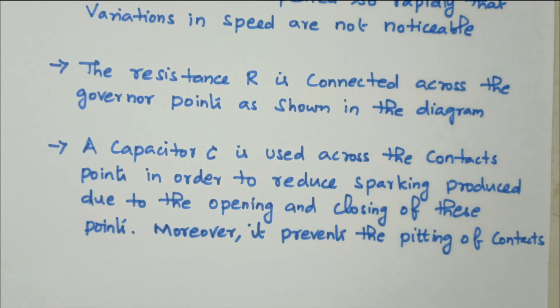The speed is set by the operator. We can set the speed accordingly. This centrifugal mechanism will open or close the switch. If the speed is high, it will open the centrifugal switch and connect the resistor, so that current flow will be controlled, thereby speed is controlled.